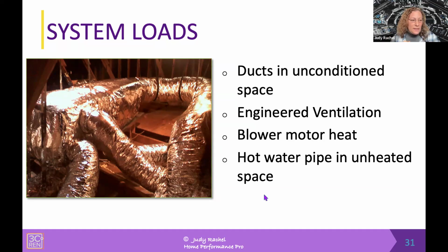Blower motor heat is something that you actually handle after you basically complete your entire load calculation. And then when you are looking at the equipment, you need to see if the equipment capacities that you're looking at include blower motor heat or not. So there's a little bit of an iterative process that goes on as you're looking at your pieces of equipment, because if the performance data that you're looking at for that piece of equipment is not including blower motor heat, then you actually need to research the blower motor heat, add that to the load calculation, and then look again to see if the loads still match that piece of equipment that you were looking at.